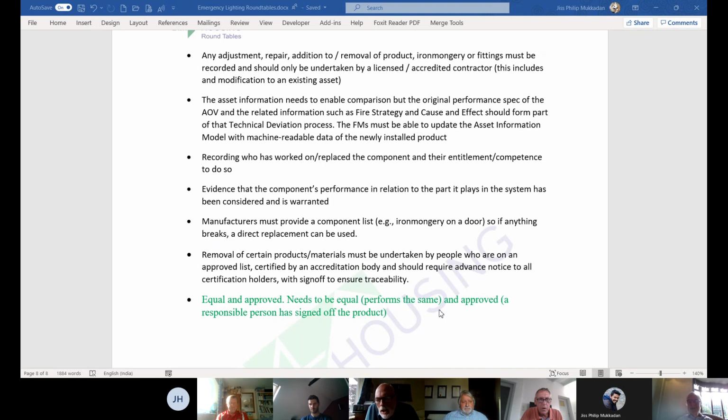Yeah. And I would agree with Jim that when the change is made, really you need a design engineer to check whether that change is adequate, not specifically to a light level, but whether it's appropriate to the application and gives the safety that's needed on site and against the risk assessment. Yes, and the engineer, when he comes on site, is not dictated to check the rest. If he's got a faulty luminaire, that's his job, just to do that one luminaire. But he should be looking at the whole interaction, including the distance between luminaires, to do his job properly.